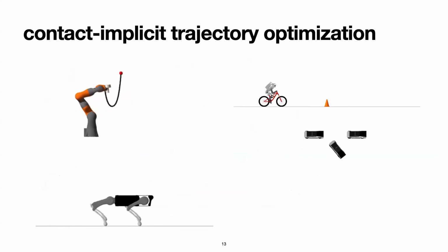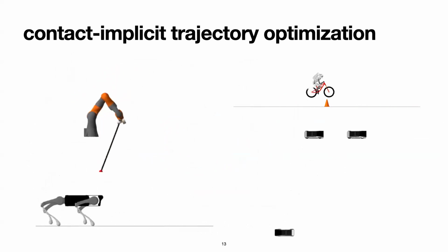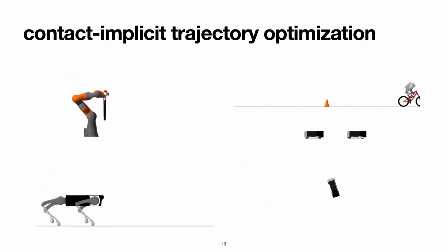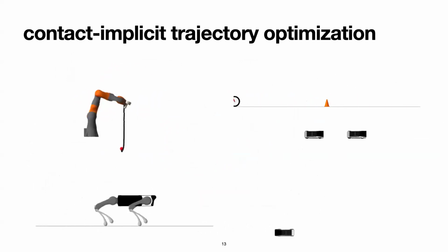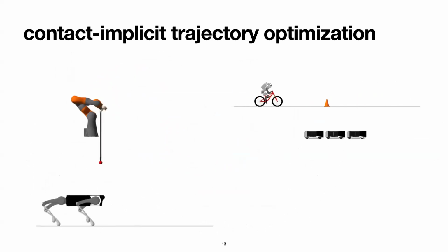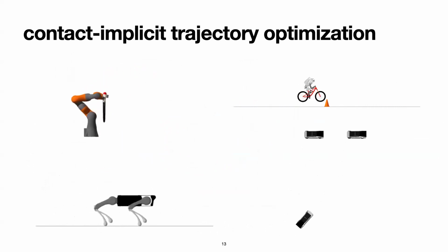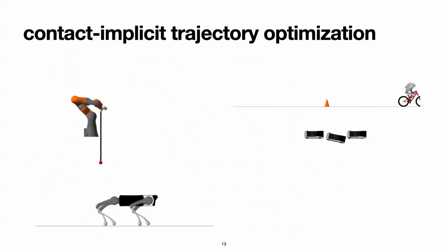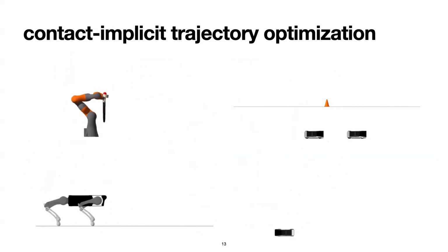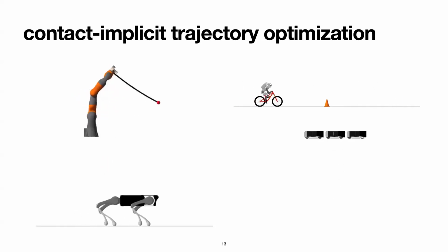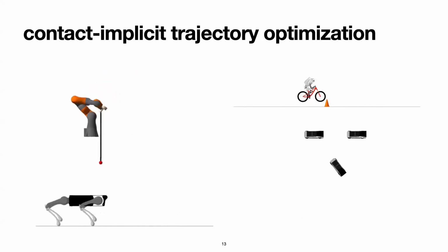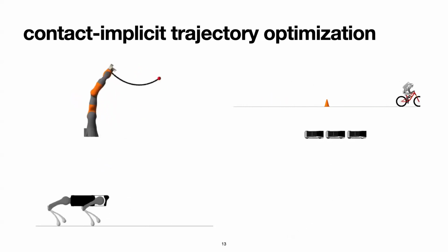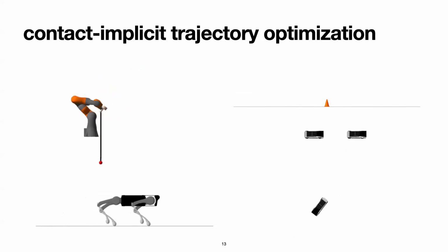The next thing I worked on that also reminded me just how hard some of this stuff is was contact implicit trajopt. So here I'm doing something very similar to optimal control, but now I'm minimizing over both the trajectory and a bunch of environmental contact forces. So relationships between the robot and the environment. As you see here, there's 4 relatively fun looking, what look like toy examples. This took months to get these 4 working. And we basically wrote a custom solver that could solve these specific problems. And it was absolutely not straightforward and no off-the-shelf solver could solve these.